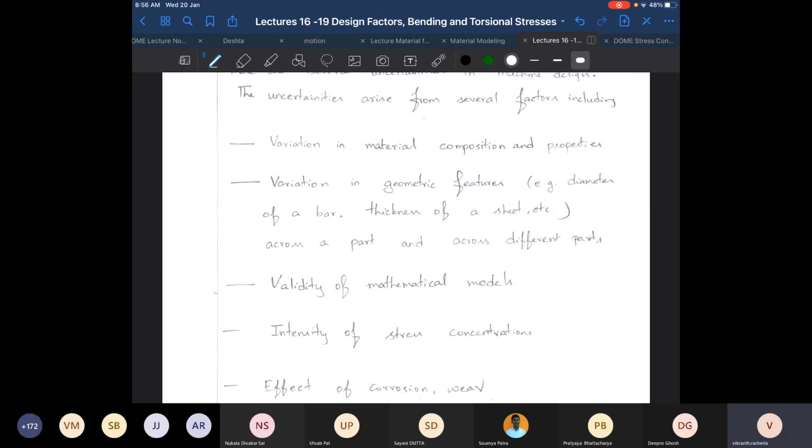One is the material perspective, with regards to which you need to know what is the strength of the material. Okay, and then you have to analyze it from the loading, geometry, and resulting stresses perspective. So you determine the stress within the component, and then you look at the strength of the material, and you ensure that the stress does not exceed the strength of the material. Broadly speaking, this is what we do.